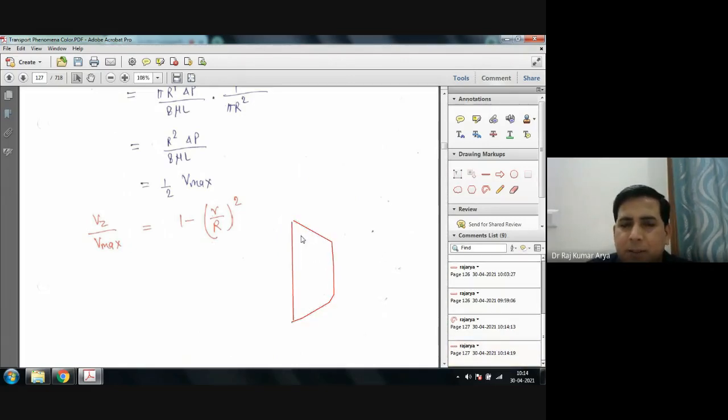So don't make it this way. This is the parabolic profile there. Now the shear stress profile is linear, and you got the maximum velocity, average velocity, and the pressure drop calculation. These are the only things we are always concerned with in the case of transport of fluid in a pipe.